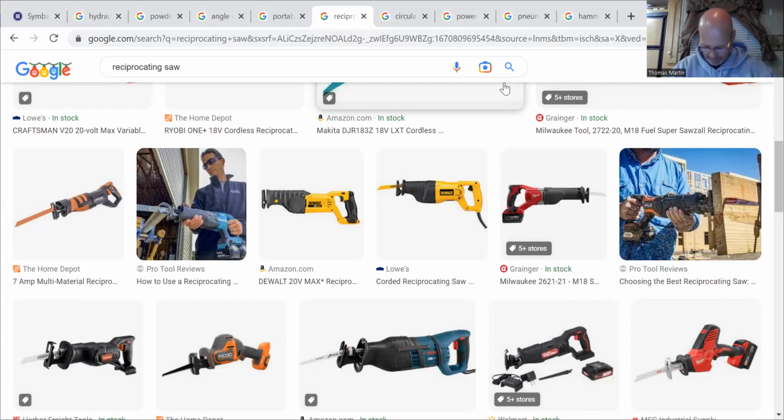2.3.2, safety and maintenance on page 21. There are a few basic guidelines that need to be followed to protect workers and the equipment when a portable bandsaw is used. First, always wear appropriate PPE: glasses, gloves, hearing protection when needed. Use only a bandsaw that has a stop.